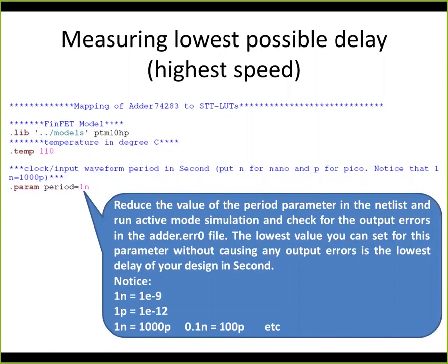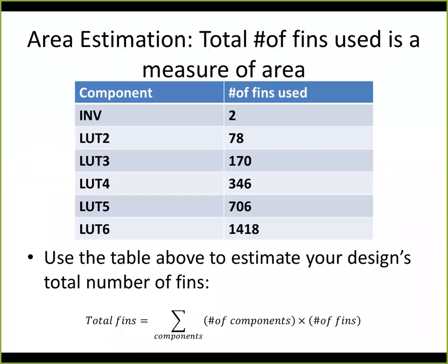And then there is a period parameter in the netlist that can be reduced in order to find the minimum possible delay for the design. And we have also developed a script that allows us to automatically search for the minimum period.